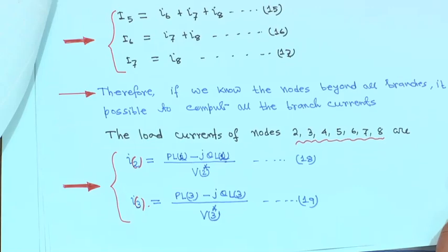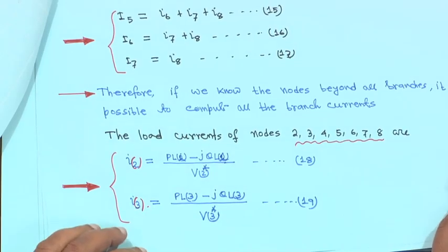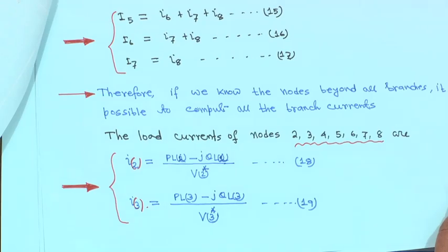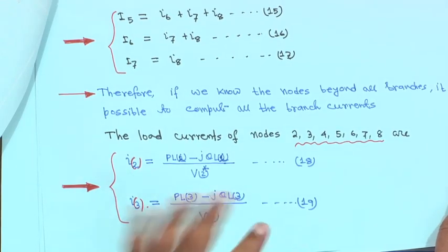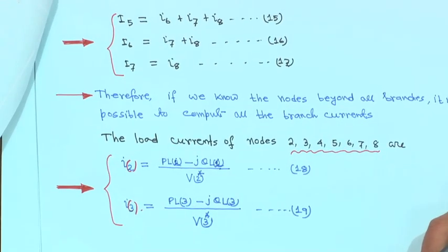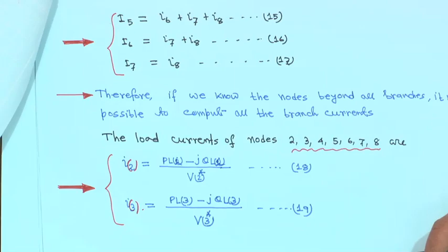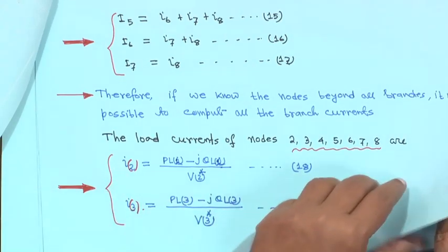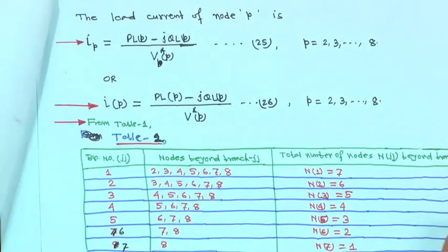So, in load flow studies you know that we start with a flat voltage. For V2, V3, V4, all these initial values, whatever is the slack bus voltage, these voltages will be considered as the slack bus voltage initially, such that the initial values of I2, I3 and all can be computed. We will come to that, right.